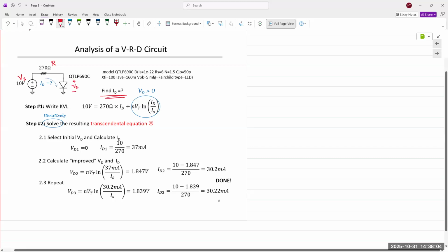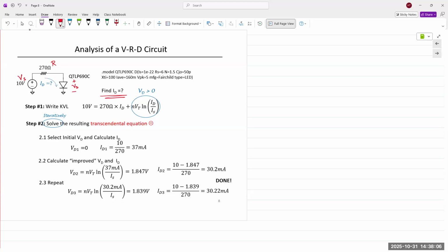Okay, simple circuit again. This circuit, by the way, is the same as the LED circuit that we talked about last class, right? We have an LED, which is a diode, and we are applying a voltage to that LED, and we try to bias that LED so that it doesn't burn out and operates within spec. So biasing helps us with fixing the voltage as well as the current that is associated with that LED. And it's the same kind of application.